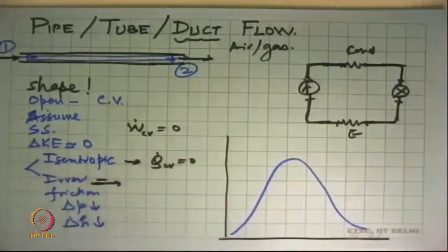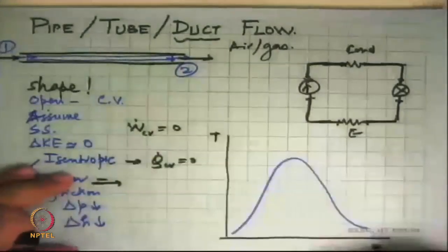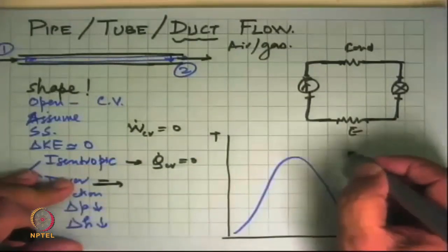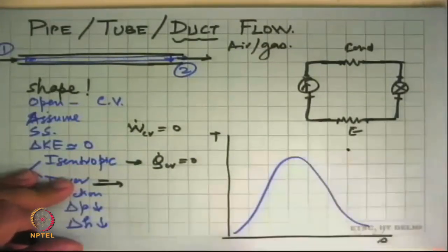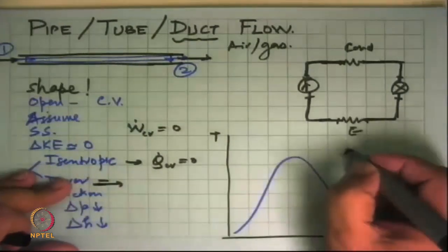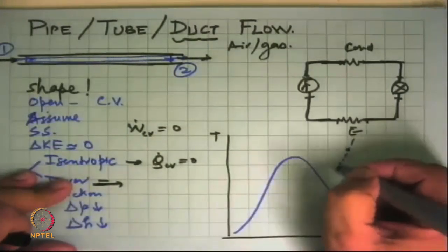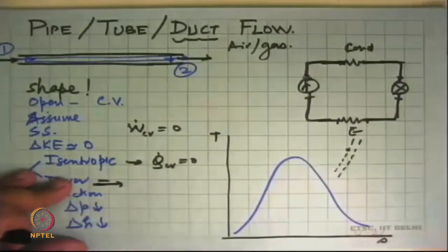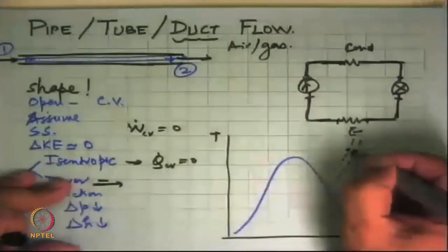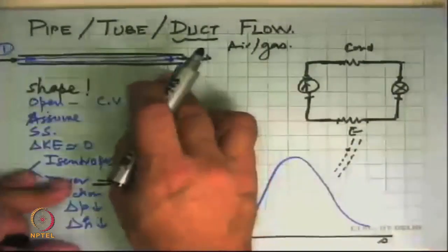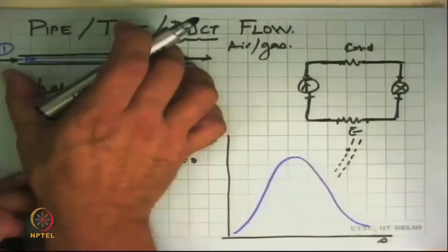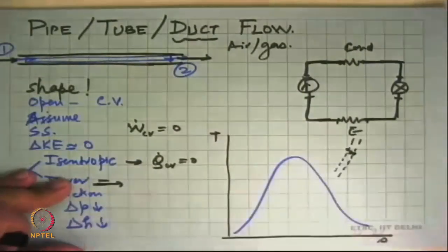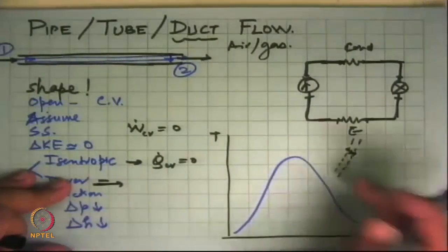if we are looking at a TS diagram, what we are saying is that if a flow is taking place, then the state will remain the same. But if it's a real flow, then this was the isobar through which this point was there. There will be a pressure drop, it will come here. Pressure drop being an irreversible process, and since there is no heat input or output, enthalpy is remaining the same, there's sort of a throttling type of a thing happening here. The state here will come down.